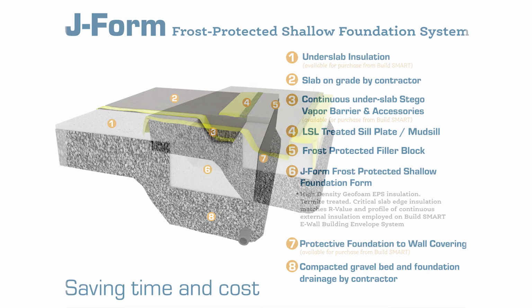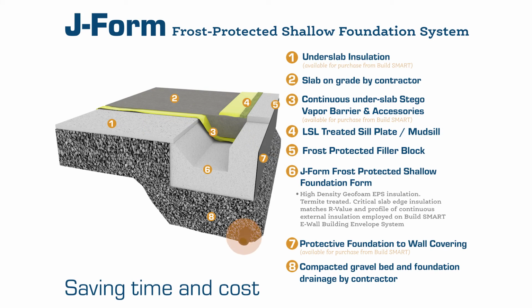If you're going down the frost depth, you dig down the frost depth, there's the foundation drain, here's your J-form, here's your underslab insulation. So in this scenario, this does not rely on any heat transfer coming out of the building. It's solely reliant on your digging down the foundation depth. And this is the most, again, universally accepted out there with the code officials and whatnot. And also, this is very compatible with what you're going to see in high performing buildings where they're trying to thermally isolate the interior conditioned space from the exterior. That's where the appetite is going to be for that.